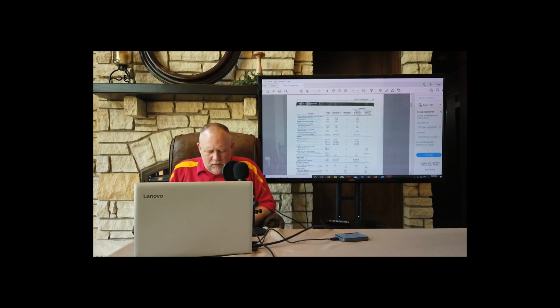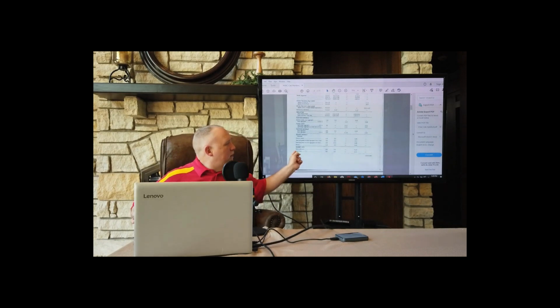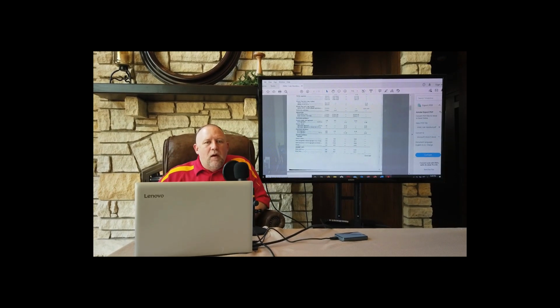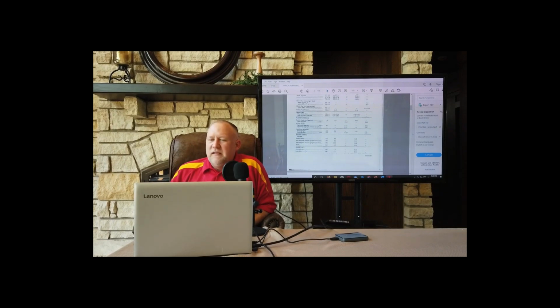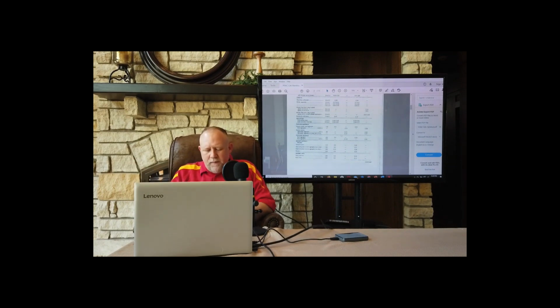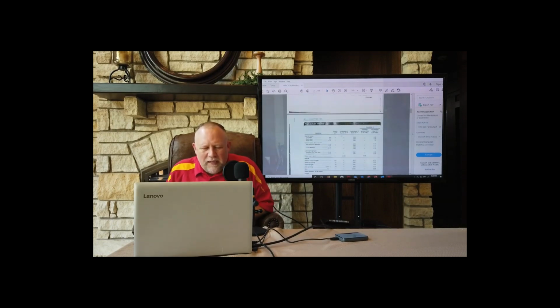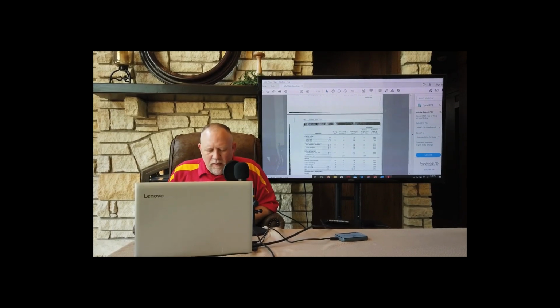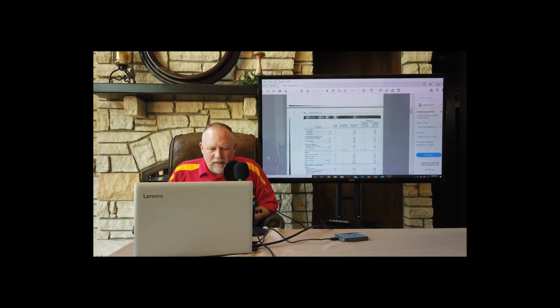Let's go down to, here we go, masonry units. And the very bottom, common brick and face brick. Most of the time, if a brick is a veneer, it's probably the face brick, that 0.11. And notice that is the thickness per inch. So if you have a 4-inch face brick, you multiply it by 4. Other common masonry units, let's go to the next page, where we've got concrete blocks. Notice there's a couple of choices.